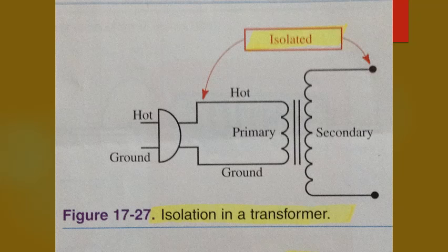Our body and hands must be joined across both leads of the secondary connections in order to receive a shock. The safety condition described above does not hold true in the primary with commercial AC provided by the power company.